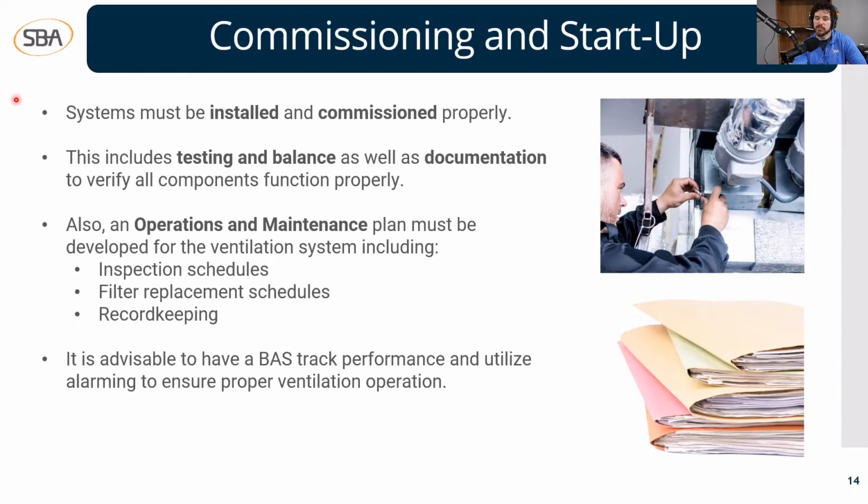We have to make sure that our sensors are calibrated. We also need to make sure that our controls respond to the demand. These are not optional. A well-designed system that's not commissioned properly is like a Ferrari with a flat tire. Just doesn't work the same.